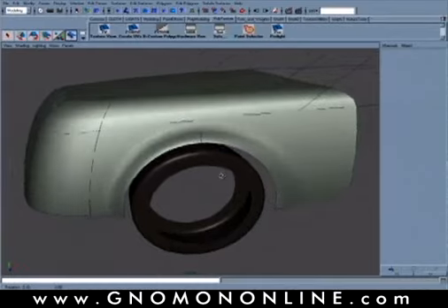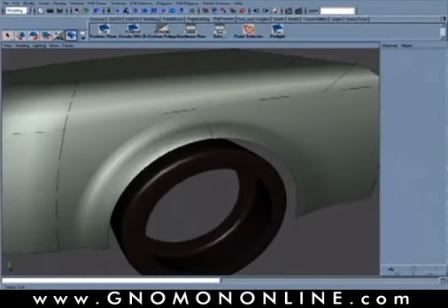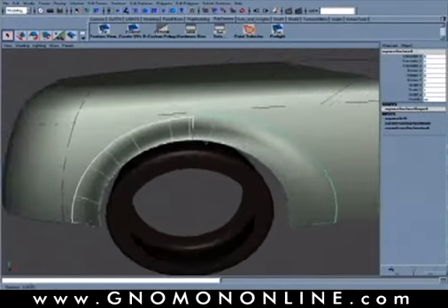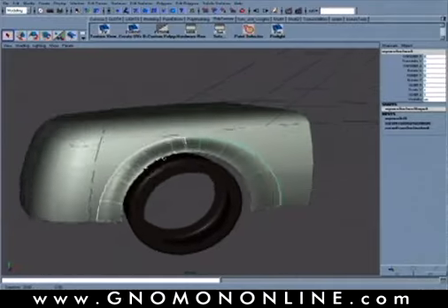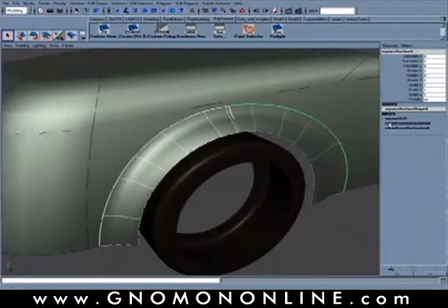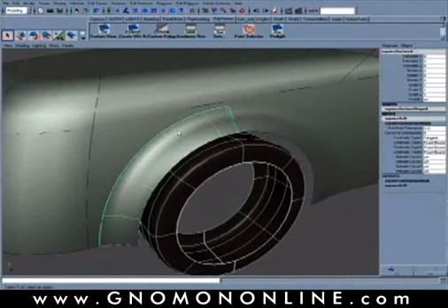Now, occasionally when you're building off a trim edge, meaning that this surface here or this surface are both built off the trim edge of a surface that already existed, it tends to put in a few more isoparms into the surface when it's being created. If you want to reduce that, you can play around with using the option of rebuilding one of these sections here.